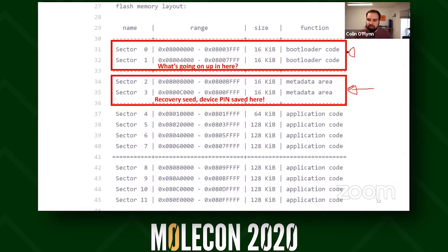There's this other code ahead of it. If you look at the addressing here, this is a lower address than here. So if we could read past an array located in the bootloader, it's just going to read through everything. We read from the bootloader and we just keep reading, and we're going to get that secret data. So what was interesting was looking at using fault injection to do that magic read.